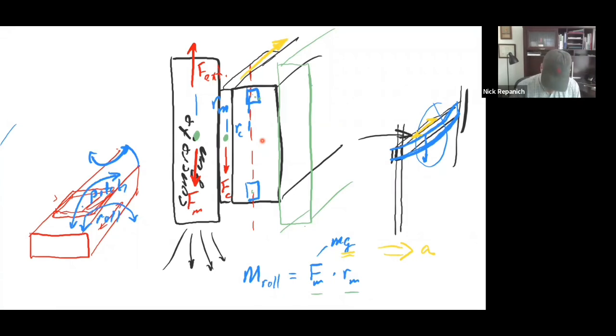In this case, as we accelerate this, if the center mass up here is on this axis right down the center, then you have a pitch moment. If though you decide the center mass is actually down here, and now you're accelerating in this direction, all of a sudden you have both pitch and, in this case, yaw, because this would tend to have a yaw motion.